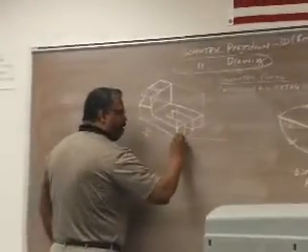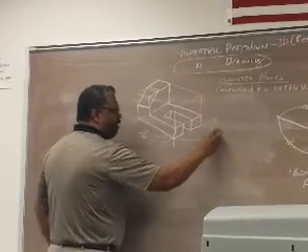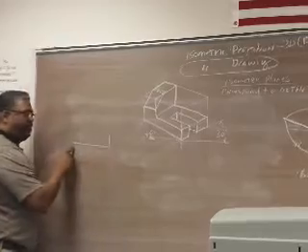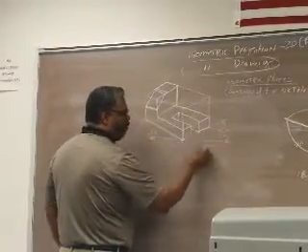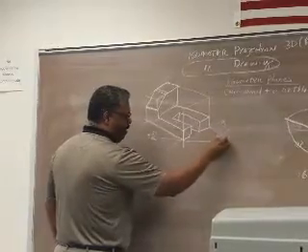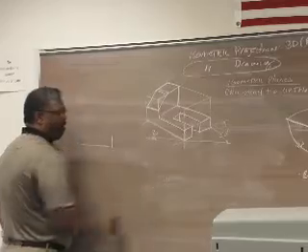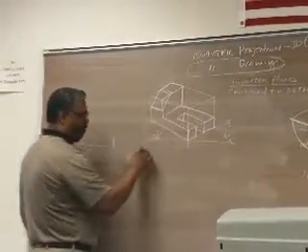It's just that my horizontal lines in my ISO are at 30 degrees. Here they're horizontal. So you have to know that. This here is true length because in my orthographic view, it would be part of my right side, and it would be a horizontal line, and it will be true length.